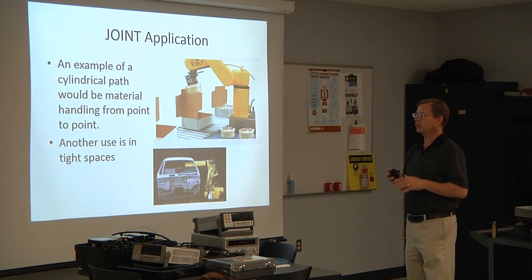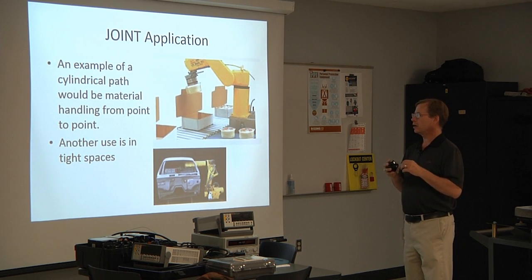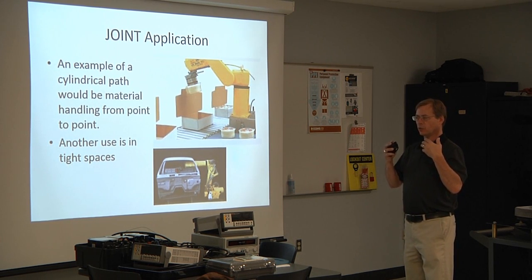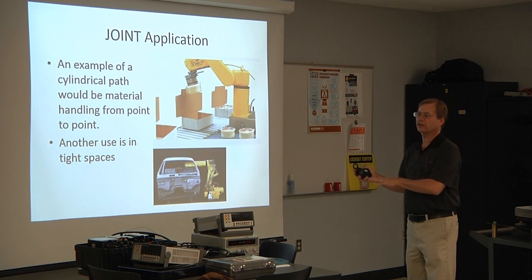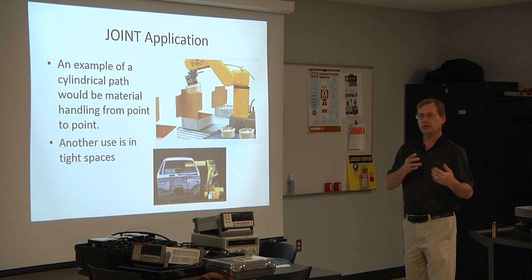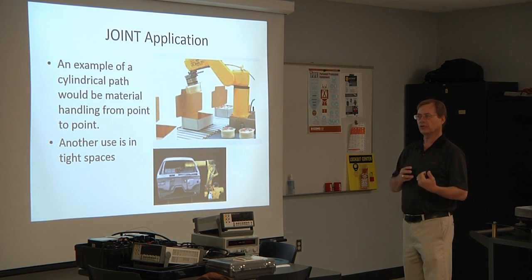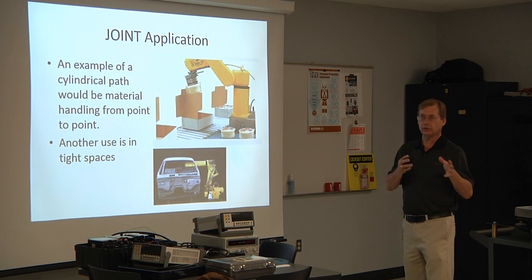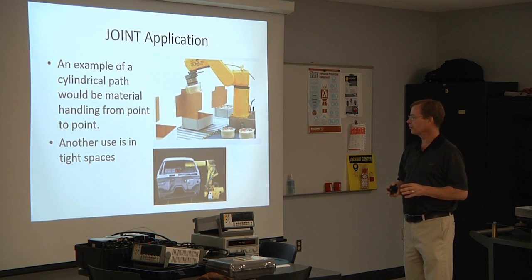So that would be one example. It's very useful when you're in manual mode, and then what you save as far as your points will be executed in the way that you told the robot to execute it. So it doesn't matter whether you use joint or some other mode to teach it. So when we talk about joint being useful, it's really useful when you're teaching or when you're in manual to move the proper arms the way you want them to move.